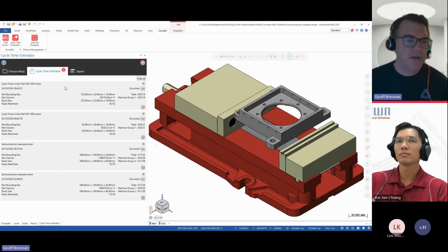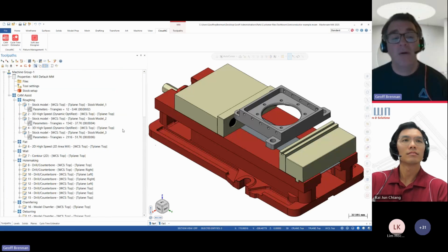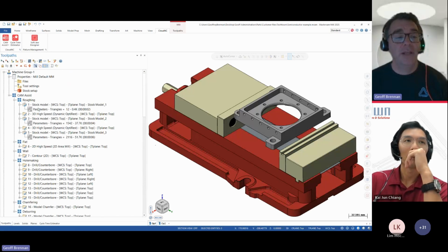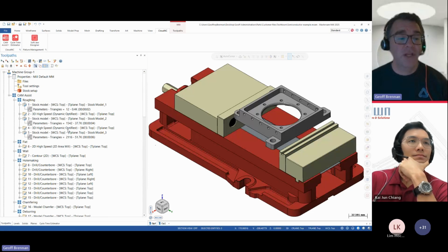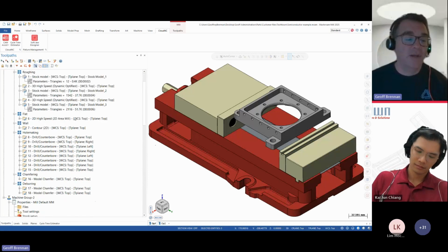So some of the things you have to do on a toolpath, you might get some output that maybe Cam Assist gets a little bit confused on, or maybe potentially it's not quite how you would do it. When we take any part and give it to 100 machinists, 100 CAM programmers, we're going to get 100 different solutions on how to machine it. So it might not be exactly to your liking, but you have the facility to edit. The output here is, of course, modifiable. You can change the ordering, you can add operations, you can take operations away, and you can correct operations.